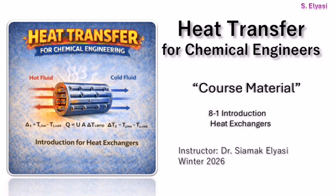First up, let's talk performance. The number one metric here is the overall heat transfer coefficient, or what we just call U. Think of it like a grade for your equipment. It tells you how easily heat is flowing. It basically combines all the resistance you get from the fluids and even the wall of the exchanger itself. And what's really crucial to get is that U is almost always limited by the slowest part of the process, like trying to transfer heat into the air versus a liquid. That's a huge difference.